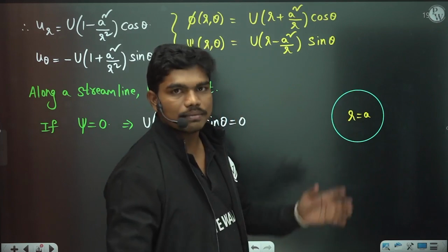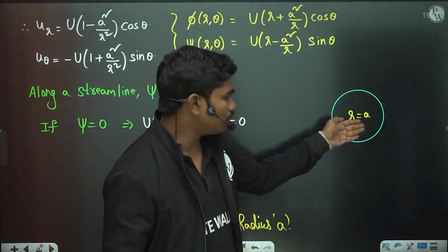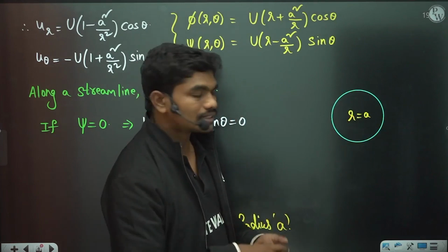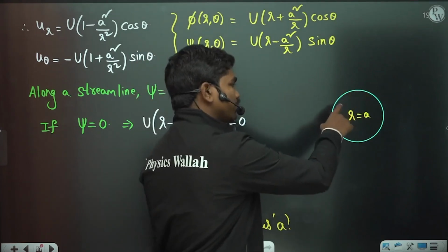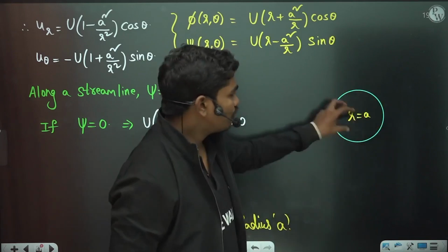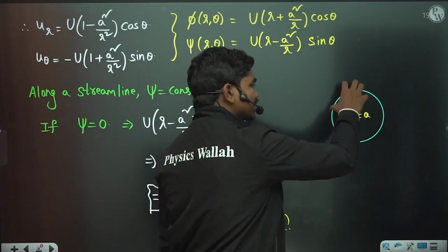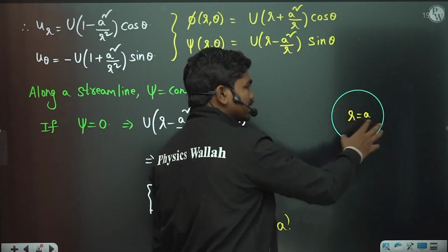We have done this analysis only in the xy plane. If you take the third dimension z, then flow around this particular streamline can be taken as flow past a cylinder, because practically this streamline acts as a solid surface, since flow cannot enter it.